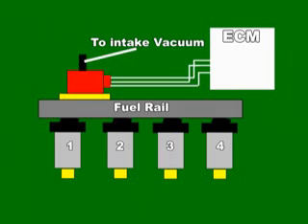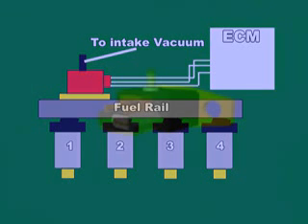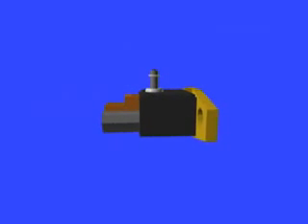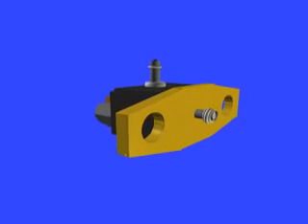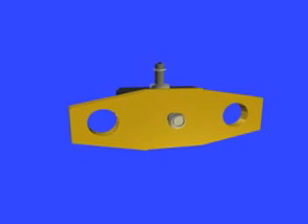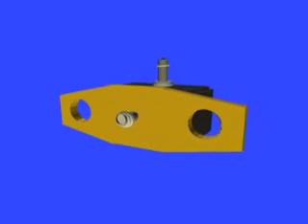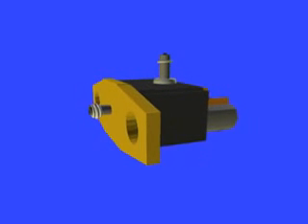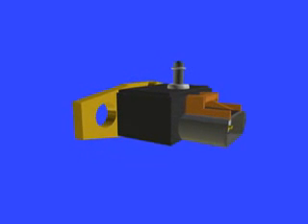By monitoring the fuel pressure, the ECM can then adjust the fuel pump's rotational speed and maintain a stable pressure. Once a stable fuel pressure is attained, the formation of fuel vapors in the fuel line itself is greatly reduced. The whole process happens very fast since it is electronically controlled.